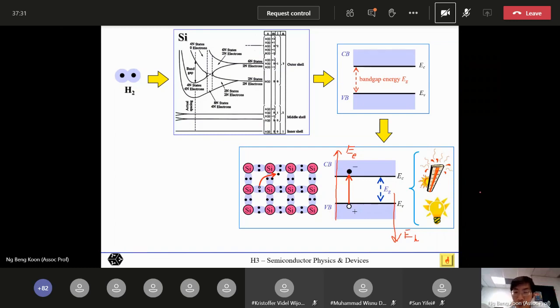So in the case of holes, the lower energy is actually going up. You can think of the hole as like a bubble. If the hole moves downwards, then it's actually going up in energy. If you think of the case of a bubble, you don't push it down; you need to exert energy to push it down. So conceptually, if you want to understand, you can think of the hole as a bubble. Then the electron is just like a regular particle in the energy band diagram.